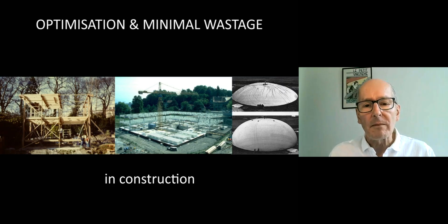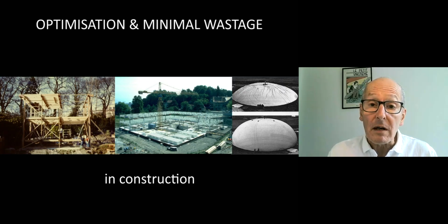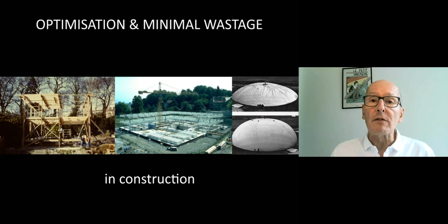Walter designed this wonderful blueprint, effectively, so that people could put buildings together with, again, minimising the amount of wet trades involved. So it was about also making it easy for self-builders, but also his blueprints involved the kind of materials that you can obtain at your local builders merchants, and the minimum amount of cutting and therefore wastage. So if it was a 3 metre long piece of timber, what you would do with it, at least, is cut it into two halves. There were no offcuts, if you like. Try to minimise the amount of offcuts, therefore minimise the amount of wastage on site.